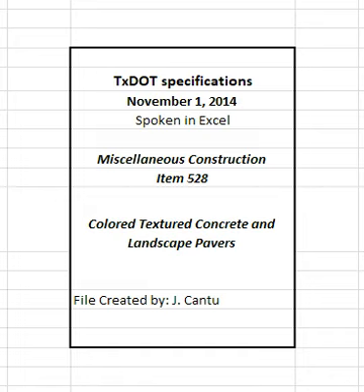2.2.2 Bedding sand. Furnish fine aggregate as specified in Item 421, hydraulic cement concrete, with the gradation given in Table 1. Table 1. Bedding sand gradation. Sieve size and percent passing. Sieve size 3/8 with 100% passing. Sieve size number 4 with 85 to 100% passing. Sieve size number 100 with 10 to 30% passing. Spread the sand at a uniform moisture content of 3% to 7%. Protect the sand against rain if it is stockpiled on site before spreading.